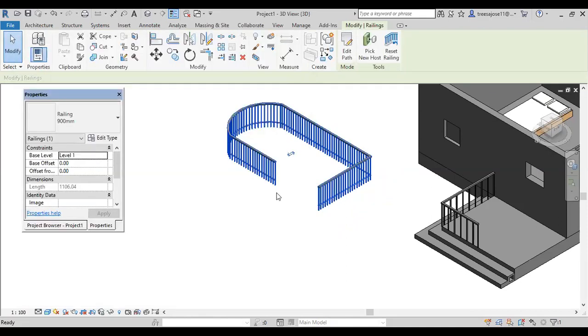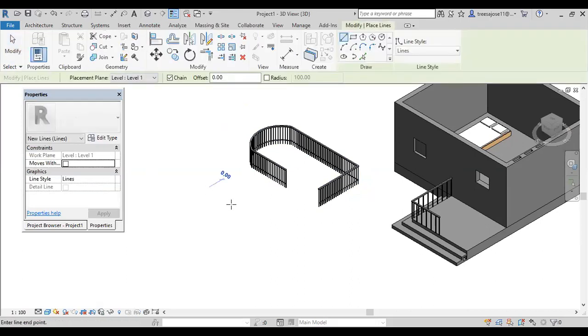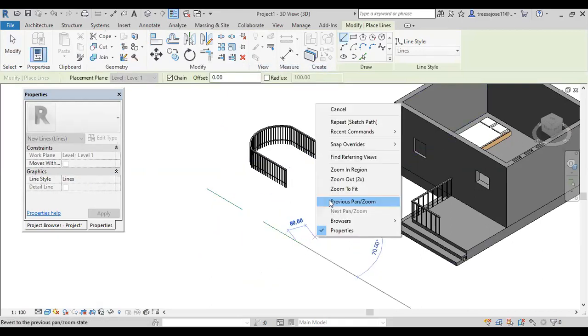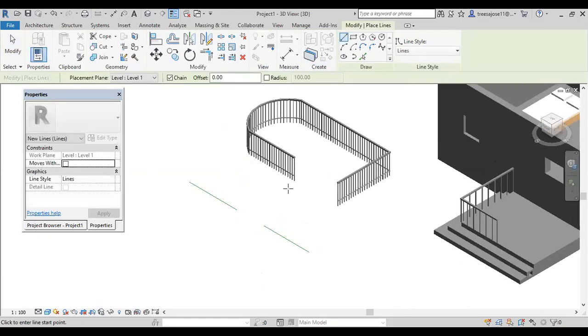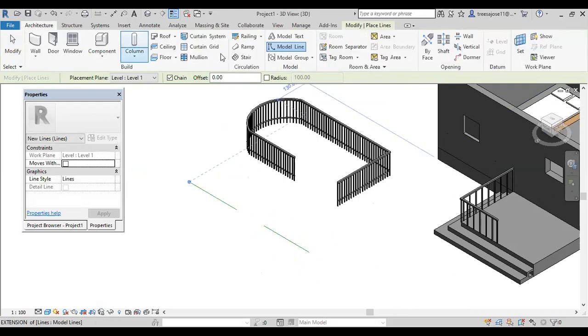Problem is maybe, for example, you have to create one rail here. For example, I will show you one model line. If I need a railing here, after that I need to finish a railing here. With the help of a single command, this is not possible. First you finish this railing command, after that you come to this command only. Okay. Let me show you railing.